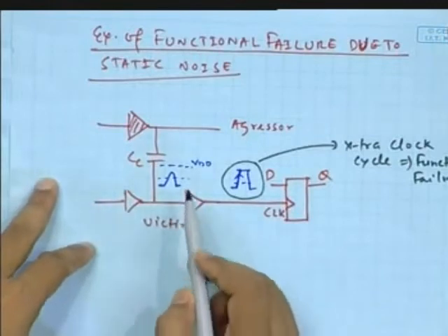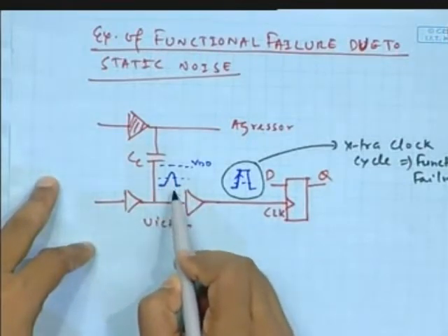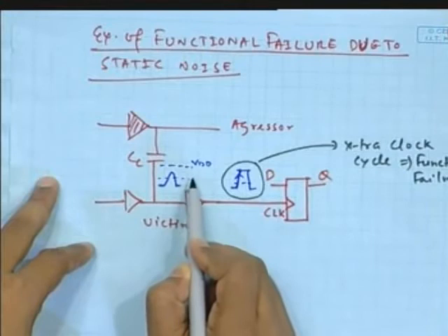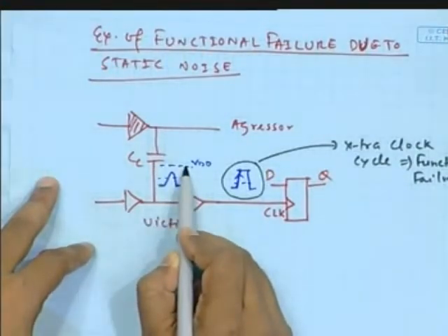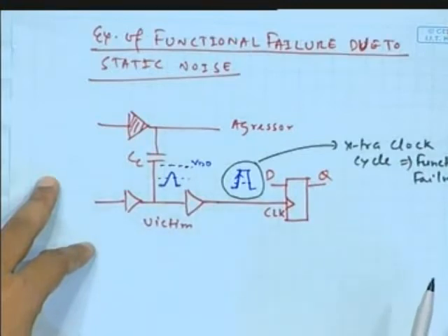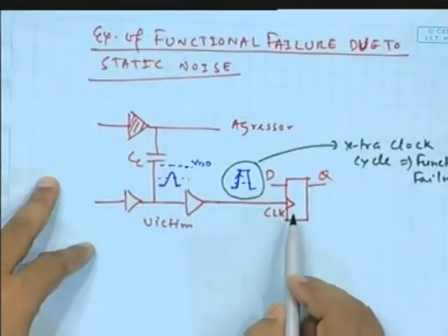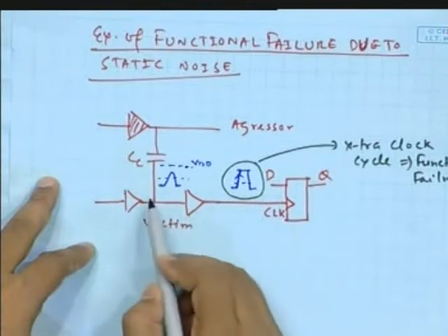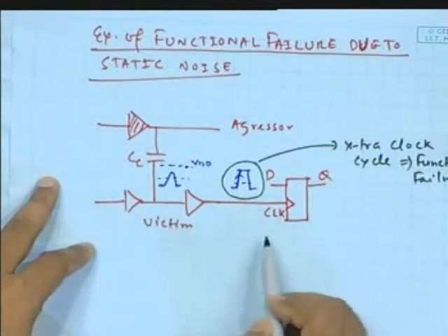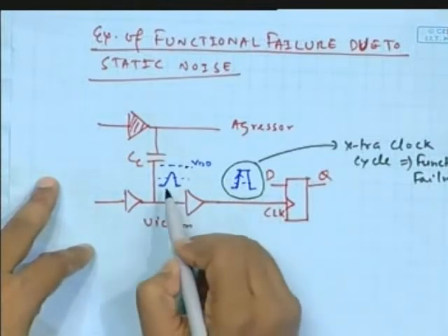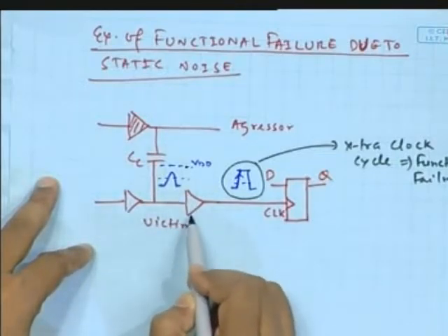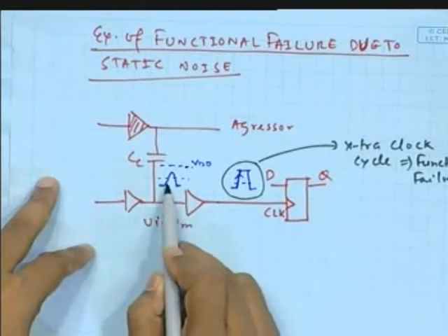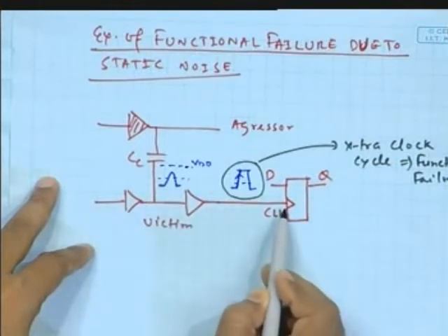So there was a small bump. So this is 0, this is VDD say, or this is some other level. I am assuming that this guy needs a sufficient bump, otherwise it cannot be latched properly. So this is very low. It doesn't make any difference. If this buffer, the clock buffer, is not there, it will simply propagate here. It won't make any difference.